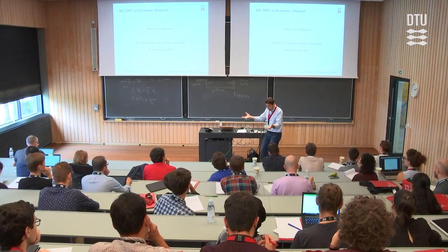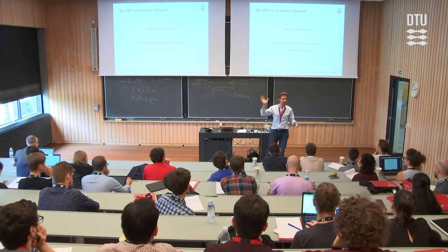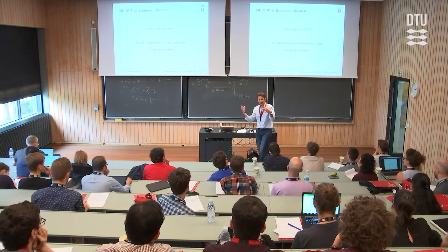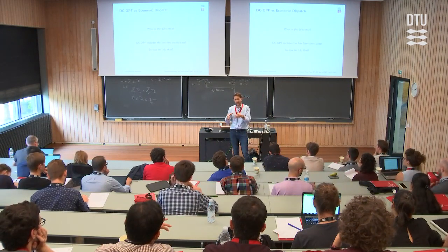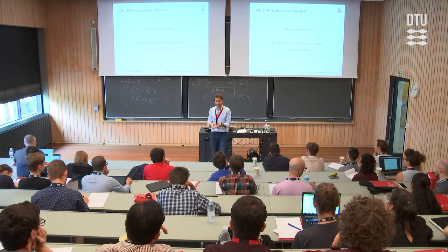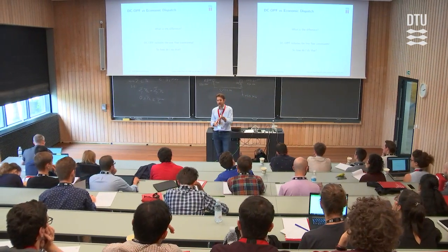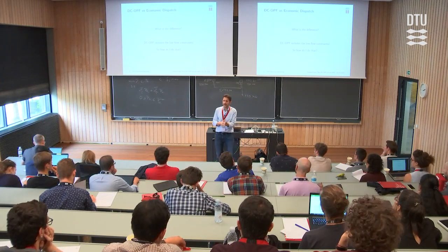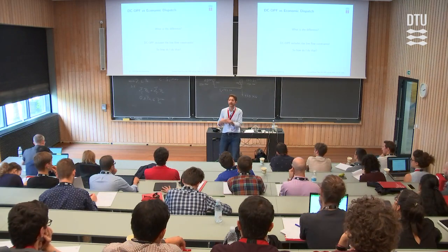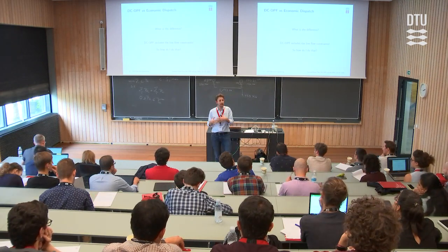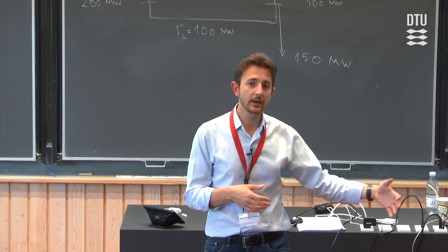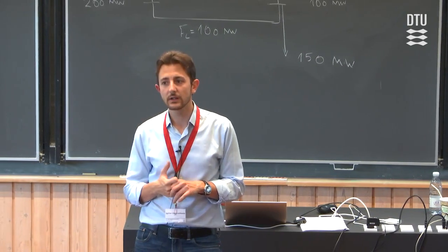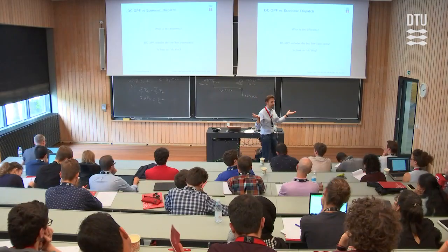So the operator takes the decision from the market, and this is not only for a power exchange with economic dispatch, also for the DC-OPF, because the DC-OPF is also an approximation, okay? So the operator takes the decisions from the market and runs power flows and tries to see, is my system secure with these decisions? If my system is not secure, I have to do redispatching, and I have to pay for that. I have to compensate the generators that were dispatched but cannot produce because it's unsecure. And I also have to pay the generators that have to operate to cover my demand. Okay? And this is how it happens. So there are two different processes.